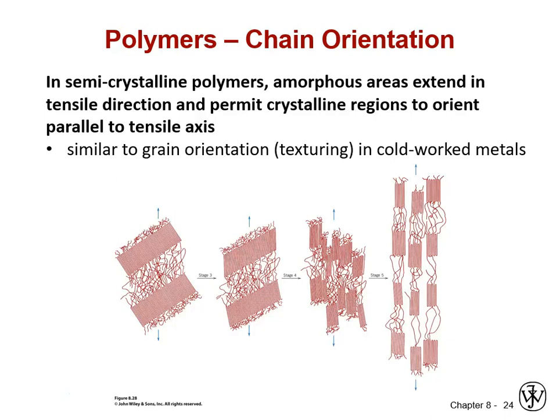If you want to think about it, polymers basically neck right from the get-go. I think we hopefully touched on that in our mechanical properties discussions. The biggest thing that you need to remember for polymer strengthening mechanisms and deformation is that their stress-strain relationships are really dominated by that spaghetti tangle of amorphous material that's between all of the crystals. That dislocation movement, while it's possible, and while it does play a role in polymer deformation, it's not the big mechanism. It's really movement of these amorphous areas that allows reorientation and reordering of the crystalline areas.